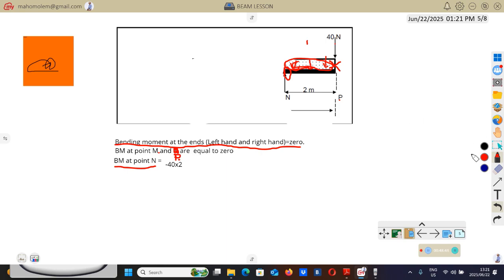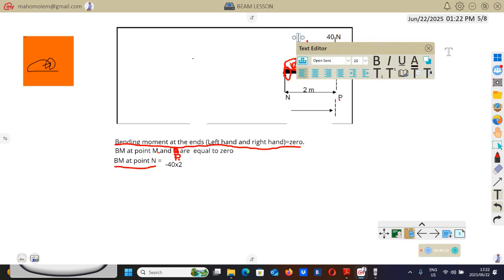And remember I said that for calculation purposes, we change that UDL to a point load. Then you put that point load at the midpoint. So we're going to draw a force here, which is acting at the midpoint. This force is going to represent the total weight of this UDL. As I've said, it's going to be that 490.